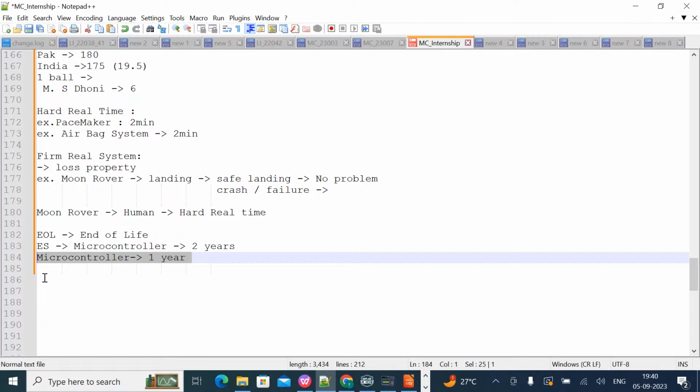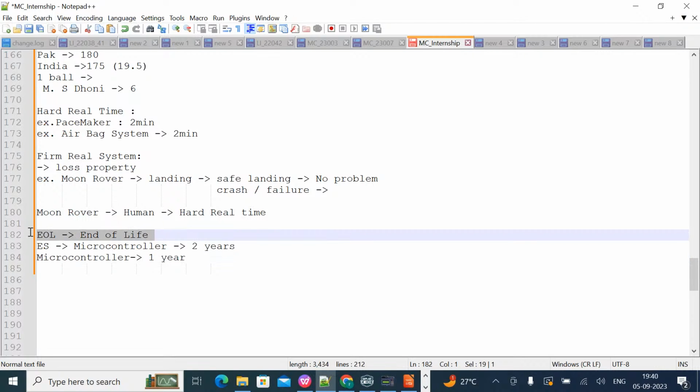So what you have to check is the availability first. For how much time the chip is available, what is the end of life. Whatever period you want, if that microcontroller is available for that particular period, then choose that one. Understood? Two ICs is fine, but if both ICs' life is going to end after a particular period, then what?